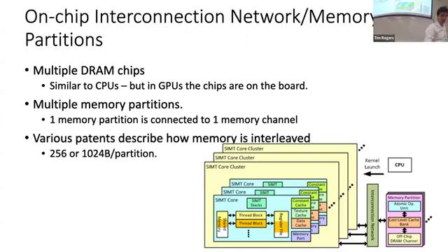Okay, so the L2 lives out here on the memory partitions, and it's spatially subdivided across each partition in a banked way. So you've essentially got a slice of the L2 for each of the memory channels in the GPU. The way the memory is arranged, we'll get to, because we'll talk a little bit more about DRAM after this slide set. For now, just assume that this is one channel. If you have a miss here, you're going to go off to the DRAM system, and we'll look at the details of that later. And the mapping here is 1-to-1. So there's one partition per channel generally.